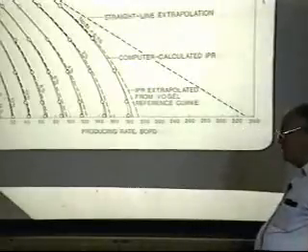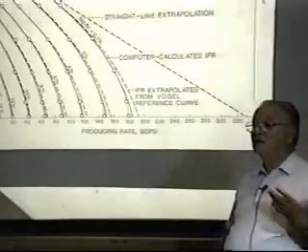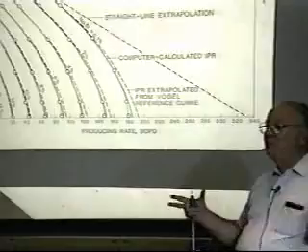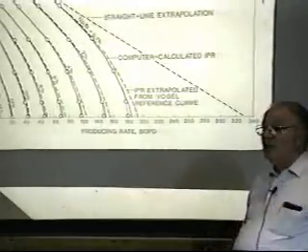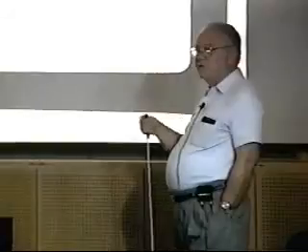When he presented it in dimensionless form, and being in the gas department, we had a dimensionless form of the back pressure equation that we used to size orifice plates when we were running multipoint tests. When I saw his paper, immediately it became apparent to me that what he's saying is that oil wells should behave just like gas wells. So I went out and got a bunch of data, including some on Ekofisk, and sure enough, when you plot the data up, it plots as a difference in pressure squared. As a back pressure curve plot, the shut-in pressure squared minus flowing pressure squared versus Q, it's a straight line on log-log.